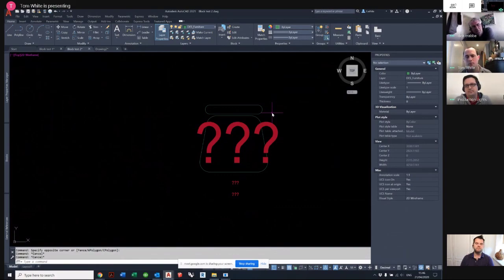So when I'm going back to the loudspeaker manufacturer's default loudspeaker symbol, I open that up, I explode it so that I can get rid of the bits that are not necessary. Then I write a new block, put that on one layer, that's the speaker there, and then put all of the other stuff, the weights, on a different layer. Is that right? Yeah, exactly.